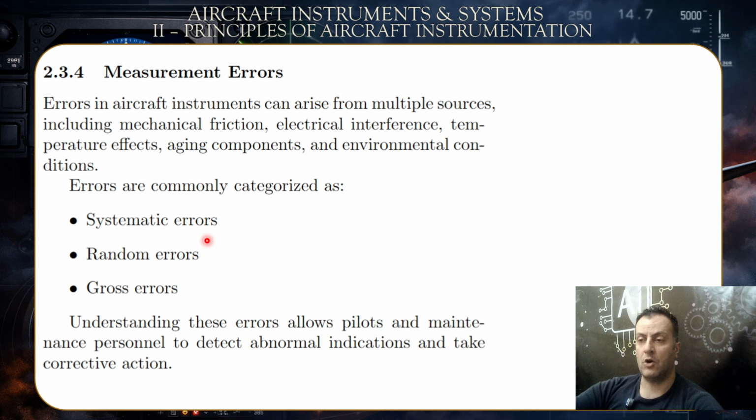Or it would be a component that at times is defective, but then it becomes active again. For example, there was a problem once on Turkish Airlines where you had, I think it was in the attitude indicator and the altimeter, which is an integrated instrument. So they had a break in the circuit. So at times, due to the vibration, the circuit would be separating.